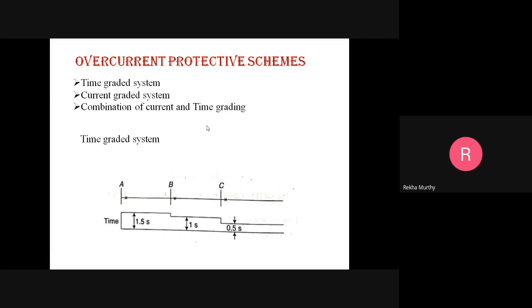This difference is to cover the operating time of the relay and the errors in the relay and CT. With fast circuit breakers and modern accurate relays, it may be possible to reduce the time further to around 0.4 seconds, or even 0.3 seconds. Now let us take these three sections and analyze.